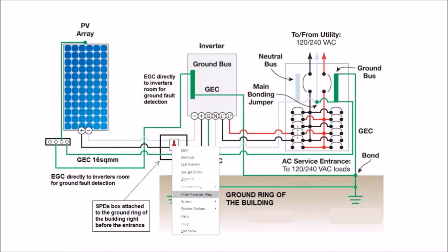In other words, from a solar designer's perspective, now here's our solar array, and it's connected to our grounding electrode conductor system. And we have a DC side, and we have an AC side. And actually, both sides need their own grounding electrode conductor. It gets a little bit confusing, but basically what you're doing is running some bare number 6 up to the rooftop and then tying that number 6 into the grounding electrode system. That's the easiest way to do it.